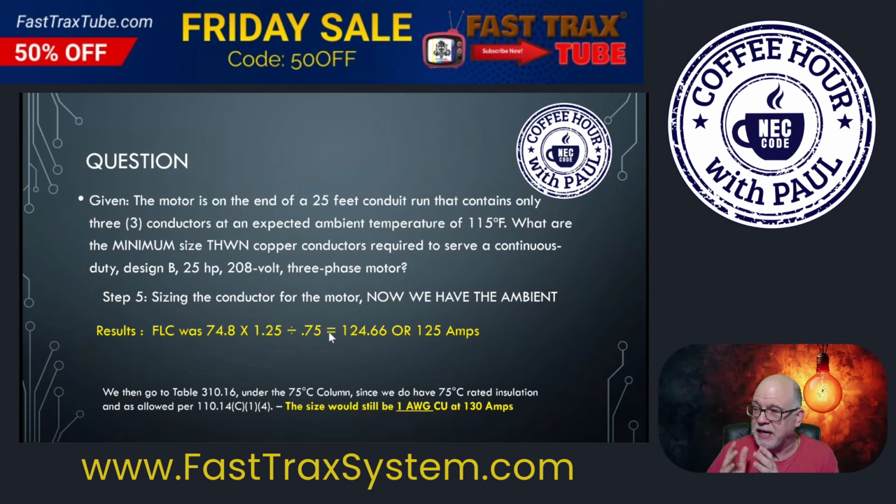So we're meeting the rules in 430.22, and we're adjusting or correcting accordingly to make sure that we're not causing any problems to the conductor or its insulation from heat buildup, things like that. Make sense? Okay, so that's how we equate it, and it's pretty straightforward. Either way, the size of our conductor is going to be 1 gauge copper instead of 3 gauge. Why? Because we had to take into consideration the ambient temperature, okay?